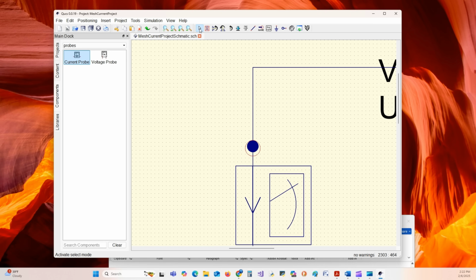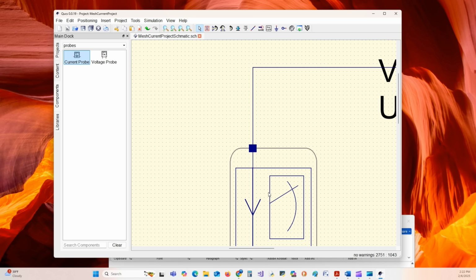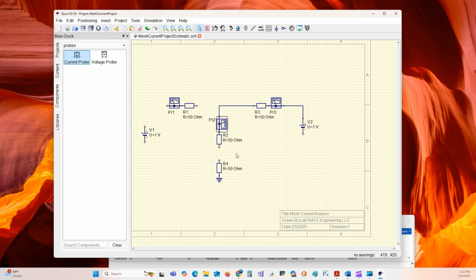This one, I tried to use the wire wrap tool, but this time I'm going to connect onto the component, the probe, and I'm going to use the cursor keys to align the probe until it goes solid black. You don't want any red circle there. So that's completed. Go back to a 1-to-1 frame, and I'm going to sign off here now and wire wrap the whole circuit, and then we'll come back and we'll simulate the circuit.